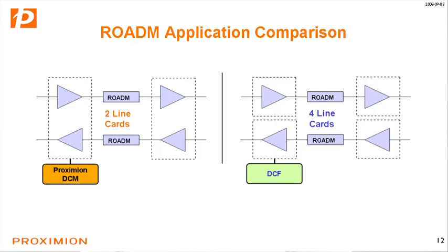The reduction in footprint can also be translated into significant system cost savings by integrating more components on a single line card. For example, the MSA and FBG DCM may be integrated on the same line card, or two amplifiers can be integrated in the same package and mounted on a single line card. This can be particularly useful in ROADM systems requiring east-west separation of amplifier stages.